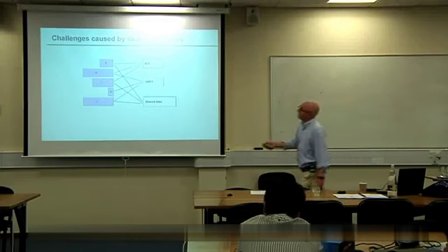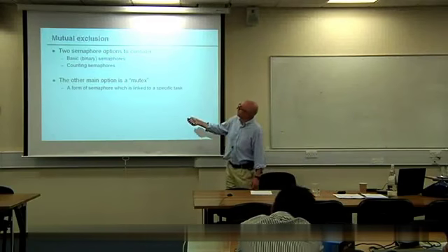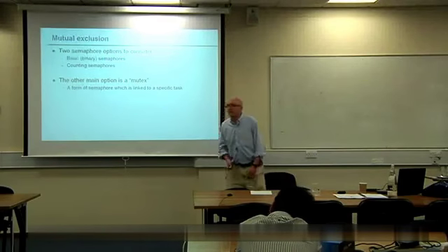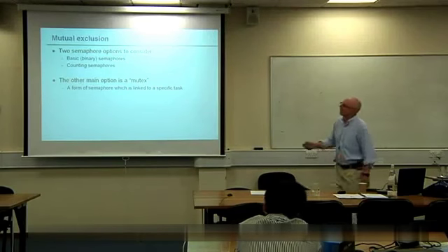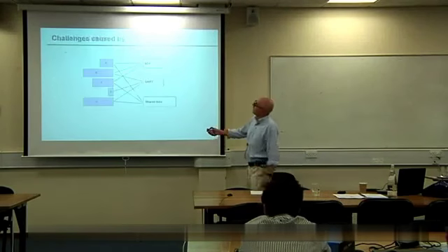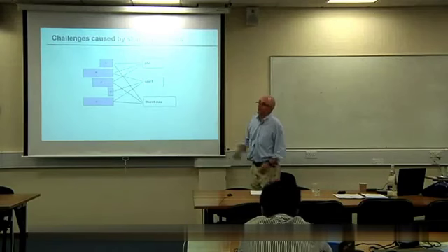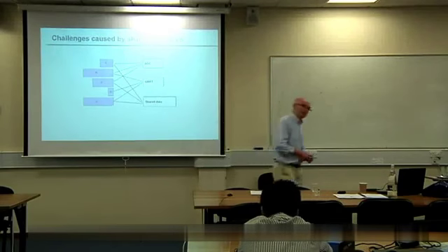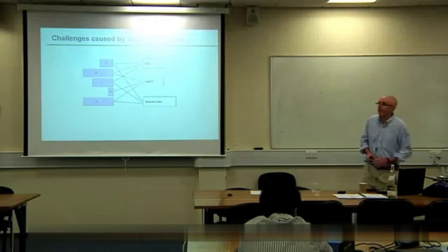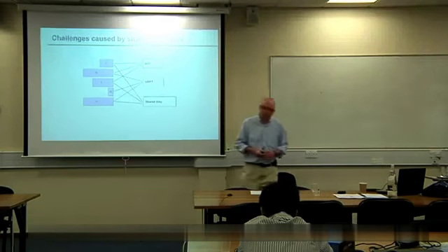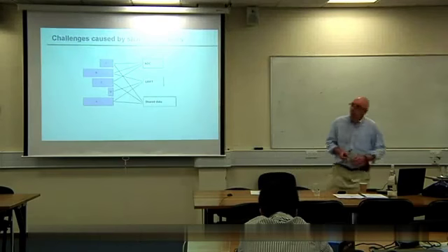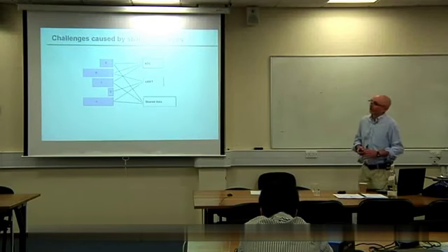So what we need to do is use some semaphores or mutexes, which we're not going to discuss here, but locking mechanisms to basically say that this task locks the ADC and says nobody else can use it now because I'm accessing it, and that's effectively what would cause the blocking of task A when it tried to execute and access the ADC.